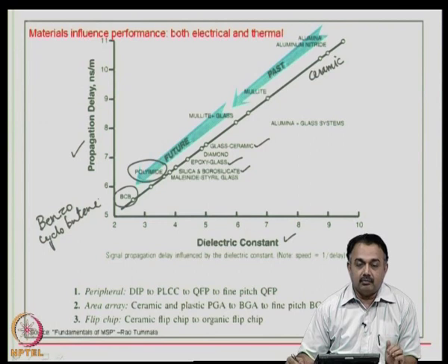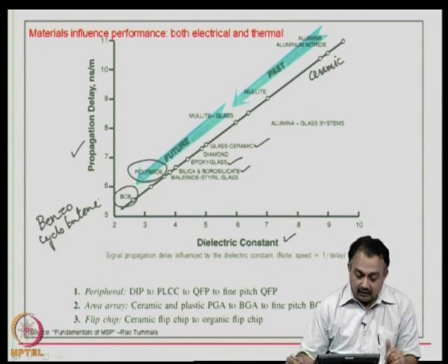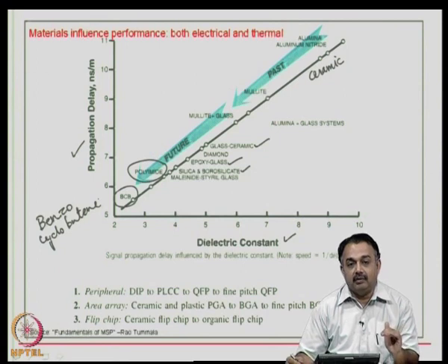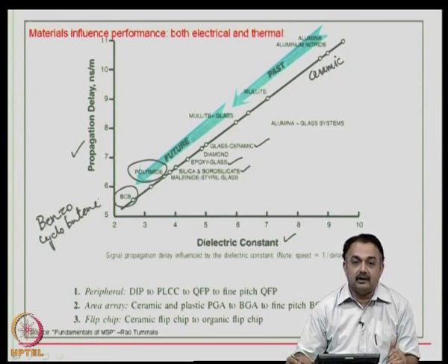Electrical parasitics could be very less if you are thinking of using it as a very thin dielectric in manufacturing. Here dielectric material choices could relate to the substrate, could relate to thin dielectric layers used in the buildup of these package substrates, and it also could mean encapsulation.